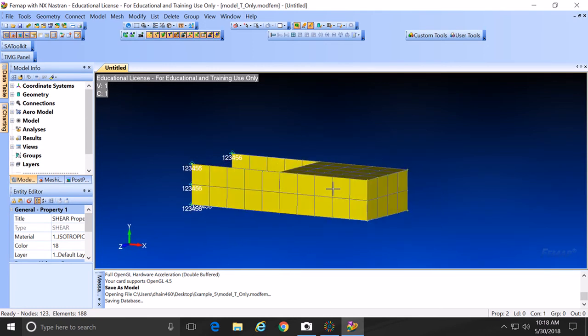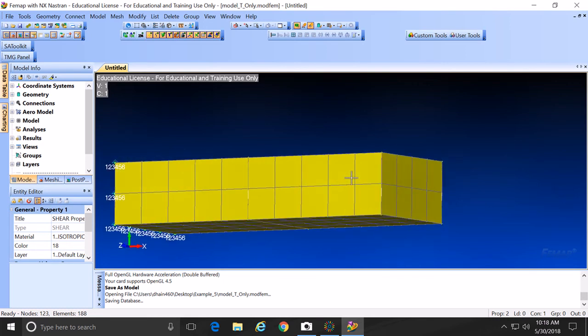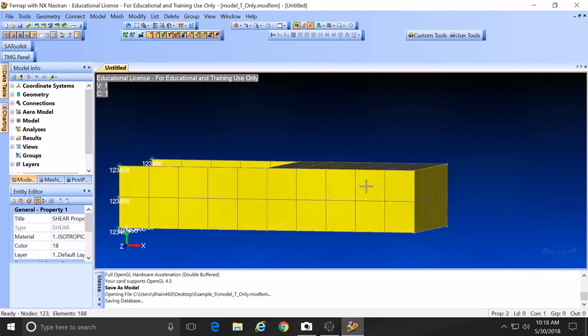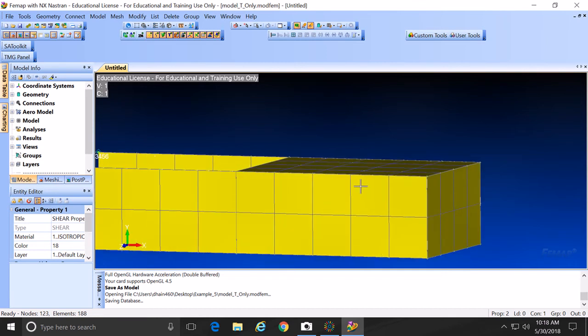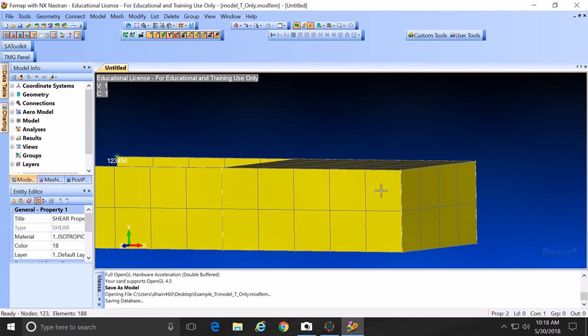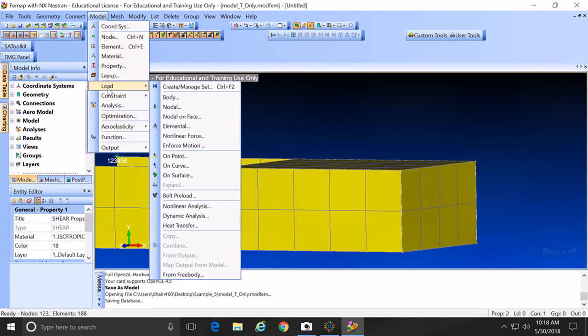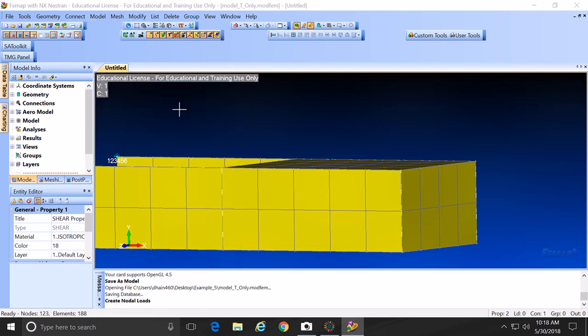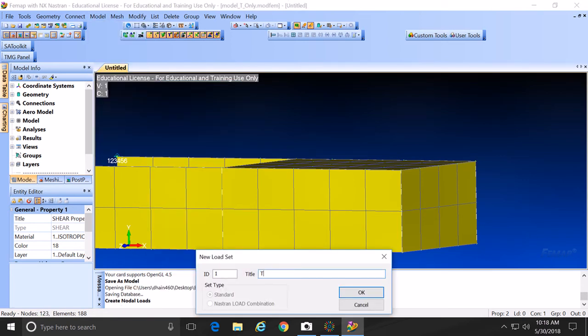Okay, now I think it's not going to give good results, but let's try because maybe it works. And if it doesn't work, I'll show you the way I would really do it, but I don't want to complicate if it's going to work in the simplest way. So now what do we need to do? We need to apply a torque right in the middle, no? So we do the same thing: model, load, on the node. If you want, just call it torque, which is equal to how much? 1,000 newton meters.